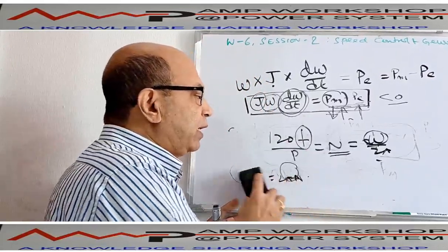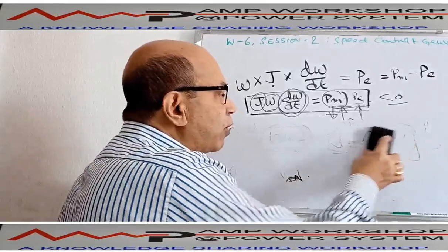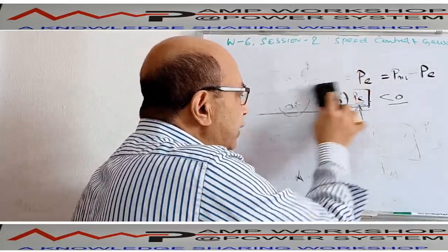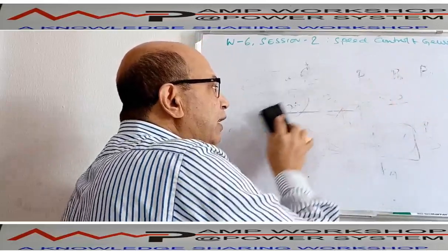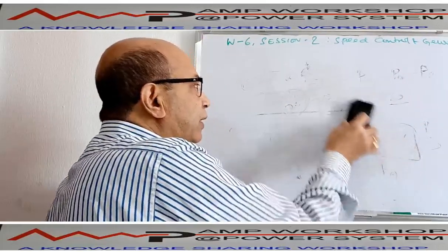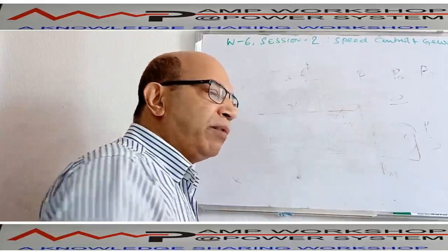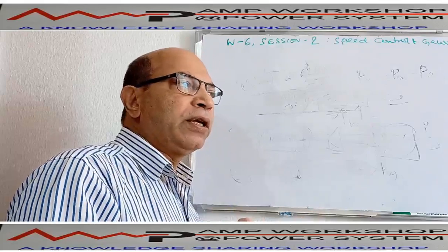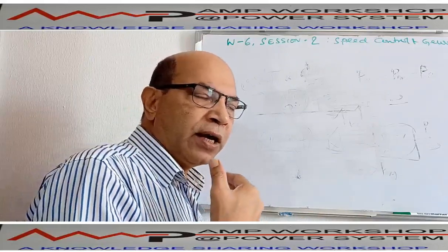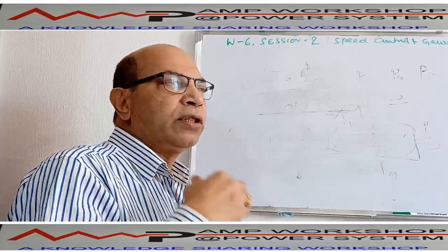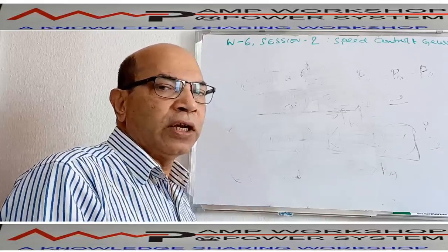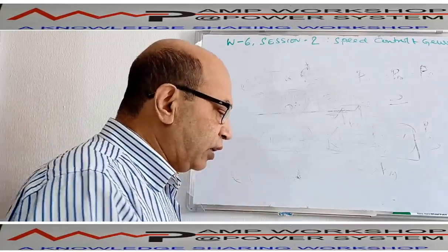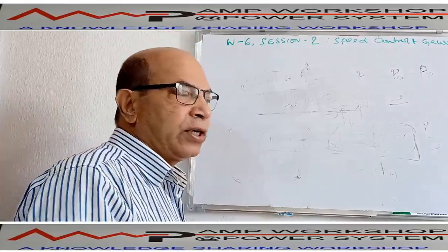You put more electrical load on the machine, that means you draw more current from the generator. In that case, the machine will be decelerated and it will produce less frequency than the rated condition. This is why, if we want to maintain the frequency of the output voltage, or in another way maintain the speed of the turbo generator set with the extra loading, we have to control the speed by suitable means. That's why a speed controller is essential for this turbo generator set.